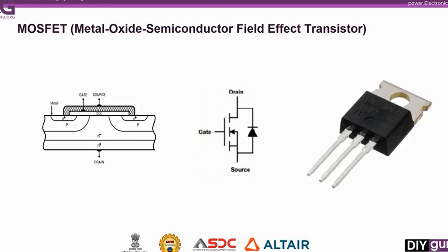Now, the gate is electrically isolated from the source, and while this provides the MOSFET with its high input impedance, it also forms a good capacitor as well. MOSFETs do not have a secondary breakdown area. Their drain to source resistance has a positive temperature coefficient, so they tend to be self-protective as well. MOSFETs have a very low on resistance and no junction voltage drop when forward biased. These features make MOSFETs an extremely attractive power supply switching device. That's why they are used almost everywhere.